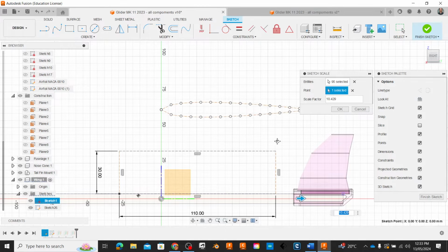I could even go out here and Control-V again. And sketch, Control-V as well. All right, if I was to loft all of those, it would just create the same wing profile all the way through. Now I need to go back into my original profile here and adapt this with a flat section at the bottom. So I need to kind of cut this off along the bottom and change the angle of this so it fits flatly onto the top of my fuselage.